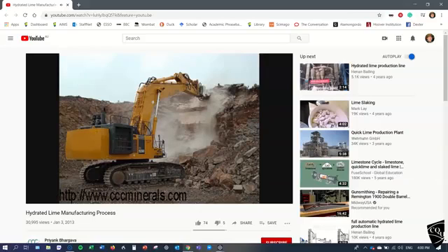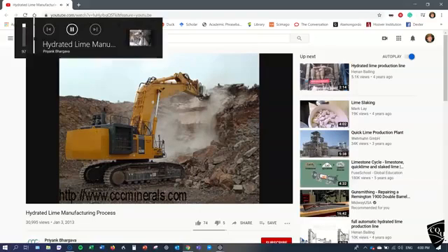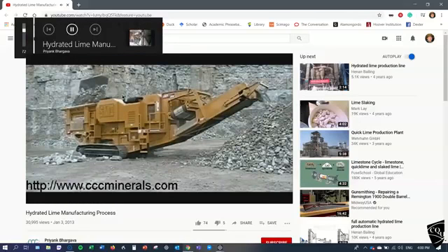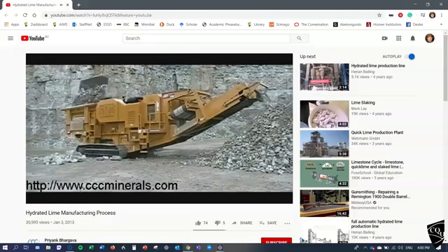In this stage, limestone is in big blocks, which are not suitable for putting in kilns. Then limestone is crushed and screened using the crusher. Limestone is normally broken into 4 to 6 inch pieces, but the size can be varied according to conditions. This process is called crushing and screening.